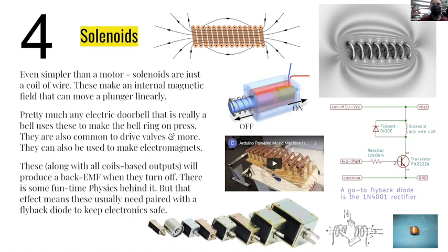One of the things about a coil of wire is that it wants to keep the current the same all the time. And so when you go to turn them off, they actually sort of don't like it. If you're willing to give me the latitude to personify them, they don't like a change in flux. So they'll induce a back EMF, and putting a flyback diode on them like this, sort of like LEDs or light up diodes. There's also ones that don't light up. This diode right here gives that back EMF a place to go. When these want to make a spike that could fry an Arduino, they probably won't.